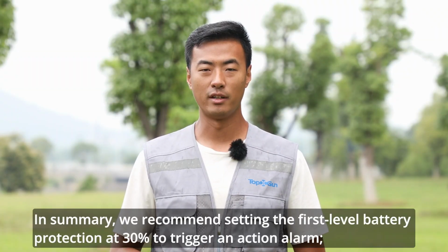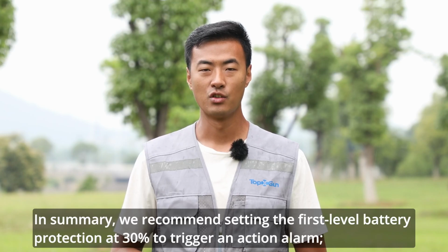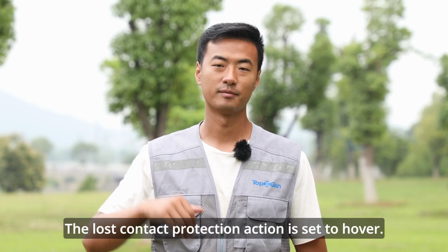In summary, we recommend setting the first level battery protection at 30% to trigger an action alarm, setting the second level battery protection at 20% to trigger an action landing. The lost contact protection action is set to hover.